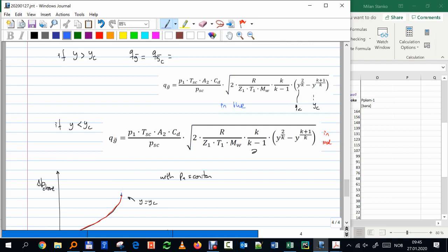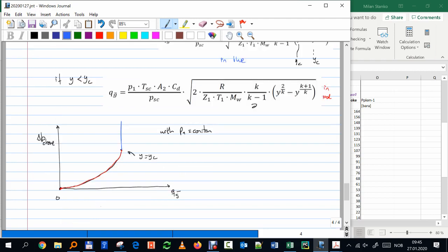Okay, that simply is a constant. So that's the choke equation. Whenever I try to circulate more and more rate, I get a bigger and bigger pressure drop. But at some point, I reach this critical condition in the throat. It doesn't matter, I cannot go higher than that velocity, or higher than that mass flow rate. Simply, I'm choked. Here I've reached critical conditions at the throat.